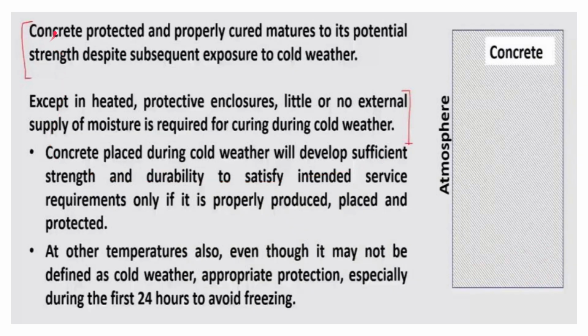Concrete protected and properly cured matures to its potential strength despite subsequent exposure to cold weather. Except in heated protective enclosures, little or no external supply of moisture is required for curing during cold weather, because the evaporation problem is not there in cold weather. So there is no external supply of moisture required, except if we artificially heat the concrete members.